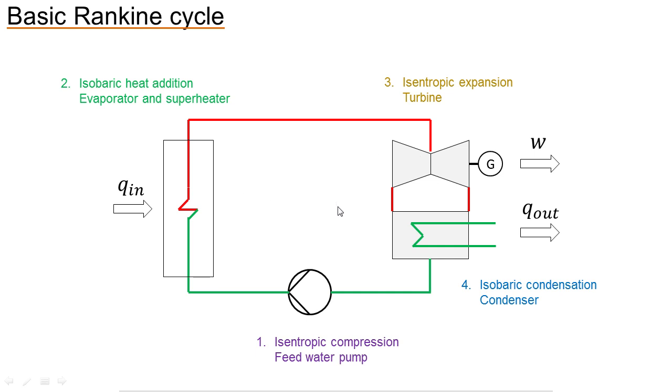This is the difference between the cycle you know from engines and the cycle in a power plant here. These things are happening all the same. This is not a cyclic process like in an engine. It's all happening at the same time, and the turbine here is the end of this isobaric process, and you get the work you put in here in the isobaric process. You get the work out of the turbine here. I hope this answers the viewer question, why don't I have work output here. I have the work output here at the turbine, and this is not a cyclic process like you have in an engine.